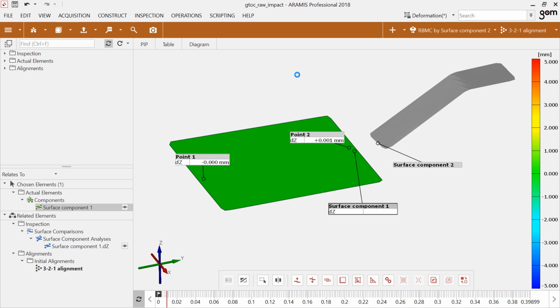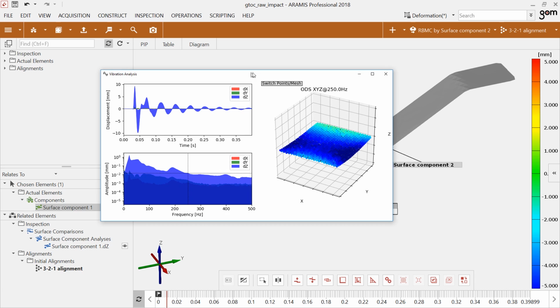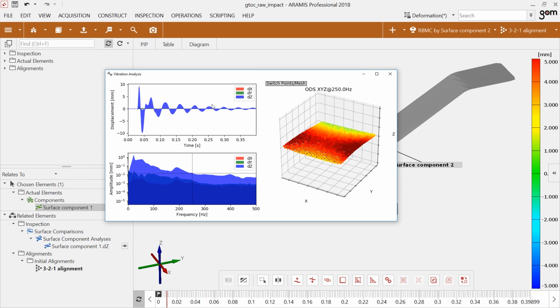This will now use the measuring data on the deflections and the shape information to calculate on the one hand the envelope curves on all displacements of all points in the three spatial directions x, y, and z, and also to carry out the Fourier transformation to have the frequency response curve.